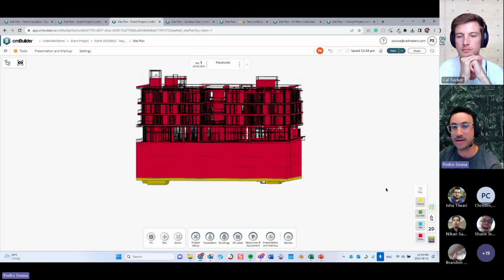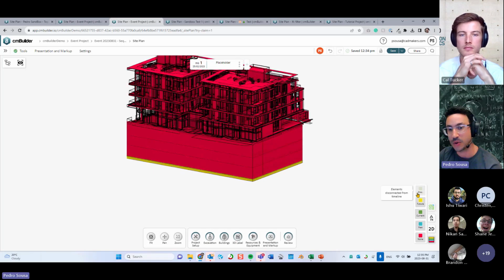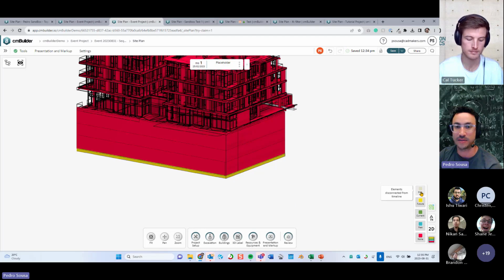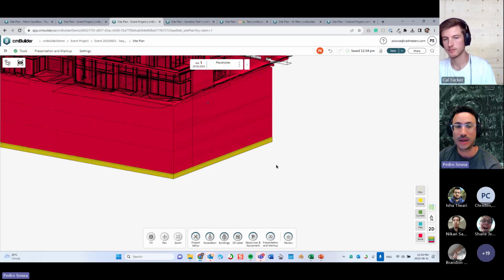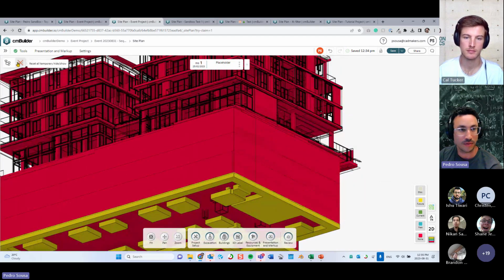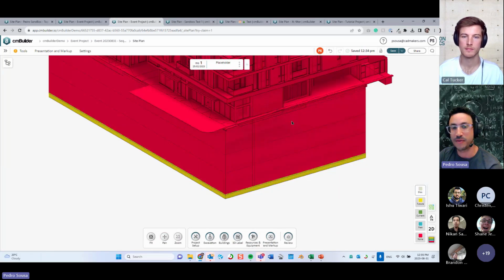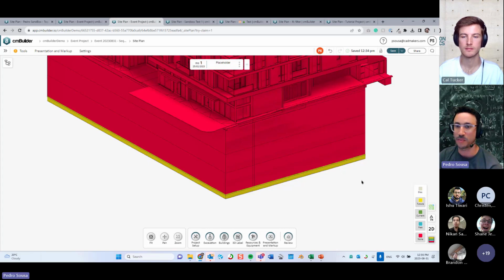Cool. And the last thing about the 3D view is using this sequencing view. Now we have a new category in here that is disconnected from timeline. This will be turned off by default, but whenever you turn it on, you will see that right now they're temporarily hidden over here. All of these beige parts are the parts that are disconnected from my timeline. Before, they were aggregated with the unsequenced elements, now you have those two separated, so you can simply remove that from your view completely.